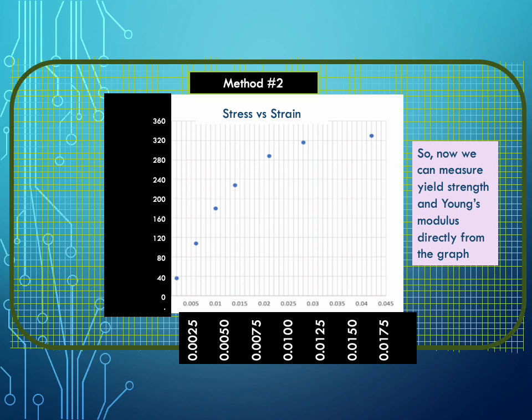All right, so again, for measuring yield strength, we take that from the graph. And the way to do that is we start with the equivalent strain of 0.002. So that's not, this point is 0.0025. So this point right here would be 0.002 strain.